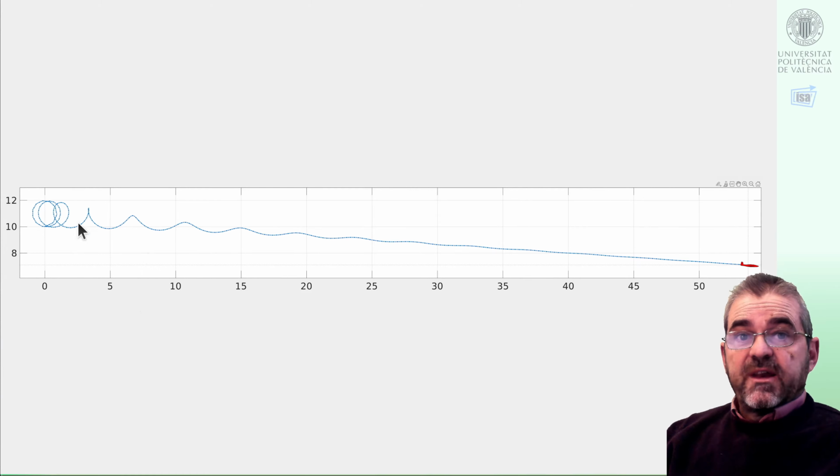And of course, when angular velocity is very high or linear speed is very low, particularly in here, maybe these simplified phugoid equations are not so reliable. But okay, the thing is that these equations approximately predict the looping behavior on a glider, because in here we are simulating zero thrust. Of course, in order to loop, we need a large initial speed. In here it is just changing a line of code, but in real life, it may imply diving down from a high altitude.